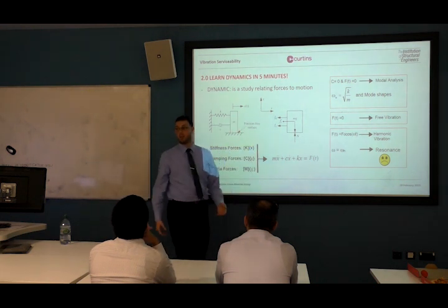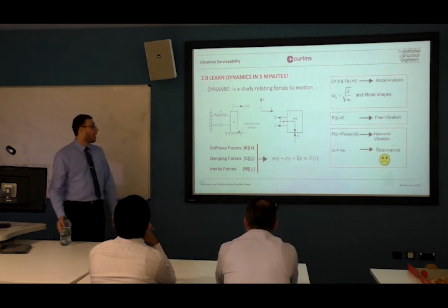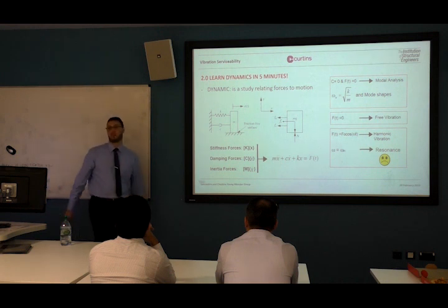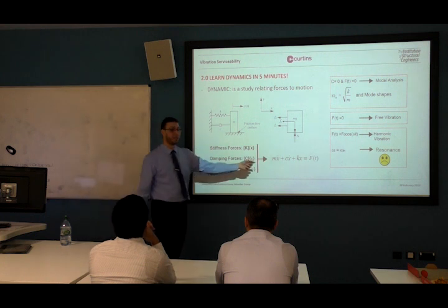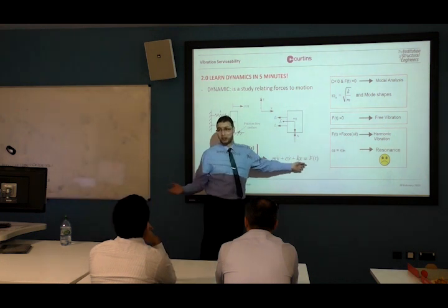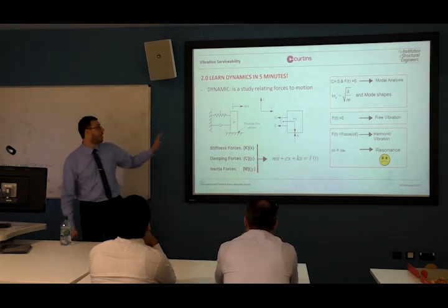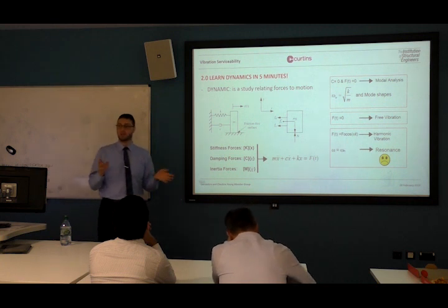So if you have damping of about 2%, you'll be expecting a response of about 50% of the input force. That's why if you go to resonance, you have a failure in dynamic design, and the structure will go mad. That's why every time we design any structure, the main purpose is to avoid